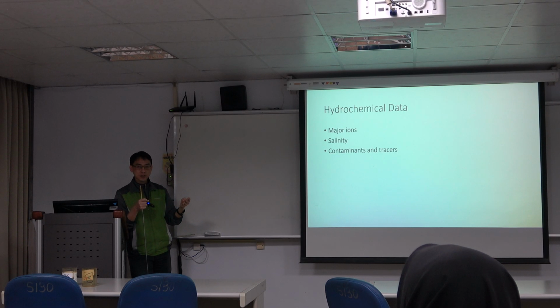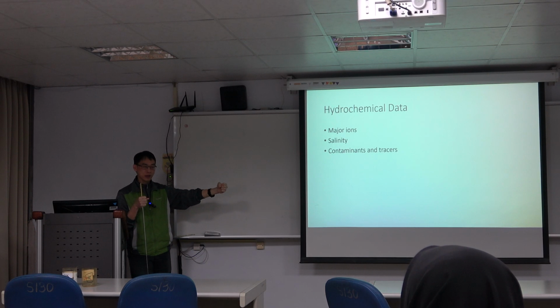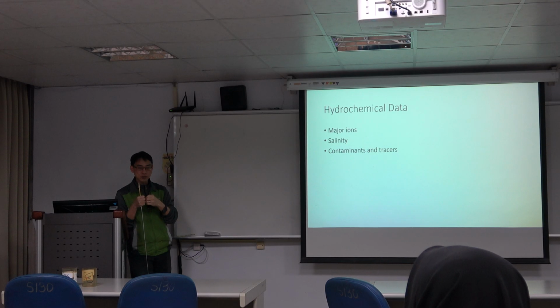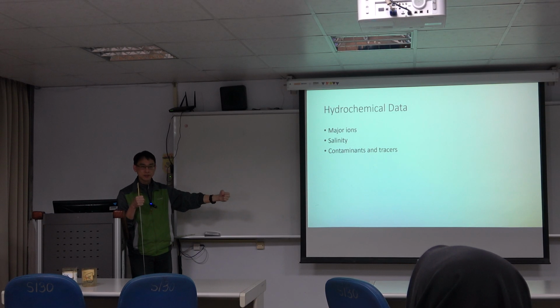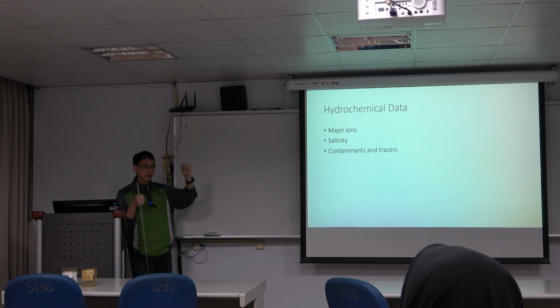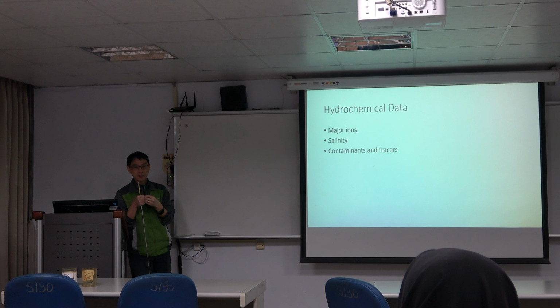Okay. That means the propagation from the injection to the production commonly takes several years. So if you want to use tracers, that means you put the tracers inside, and it might take several years to reach your pumping wells. And after you get the data, you have already run several years, so how can this data be used?